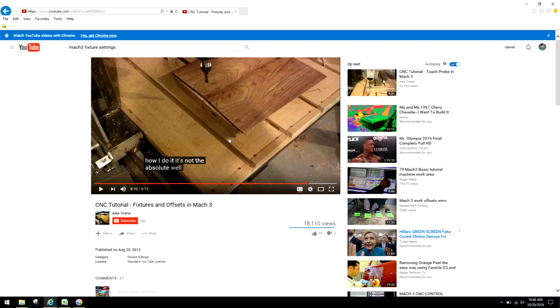So it's very simple. If there's no material on the table, you're not making money. You're making money when this material is placed on the table, you know you're good to go, and all you're doing is switching the material, hitting the fixture setting. You might be changing and setting the Z-axis as far as any width changes or tool changes that are to be implemented, and other than that, you're ready to go. So hopefully this video has been informative as far as understanding homing better, at least in my terminology,